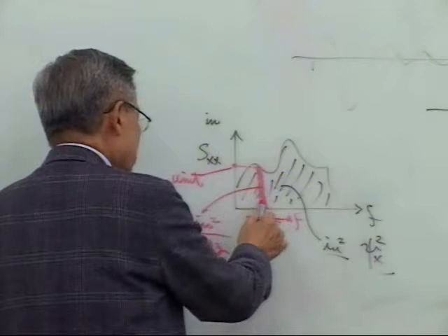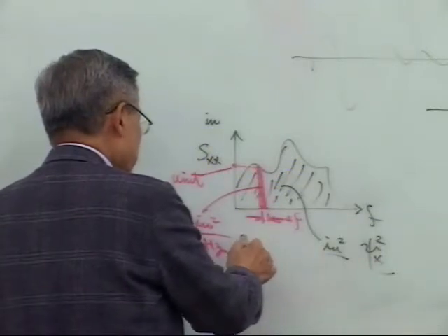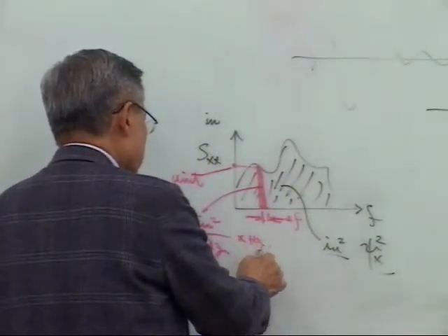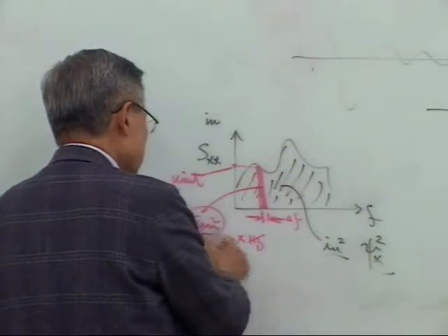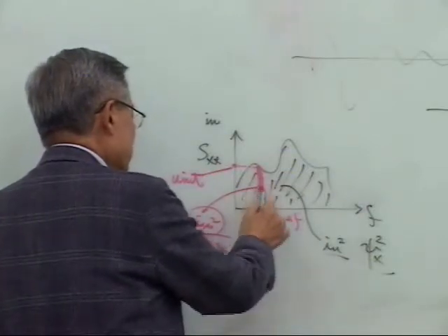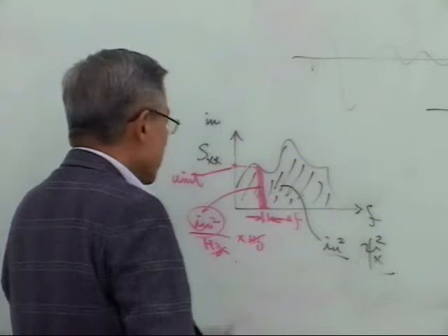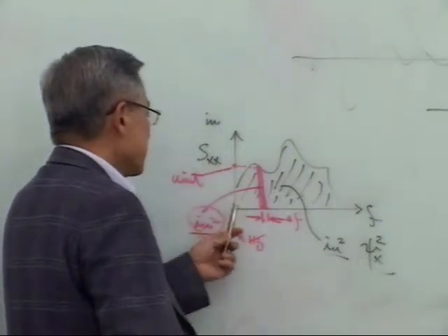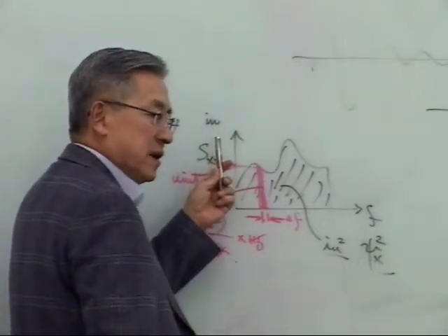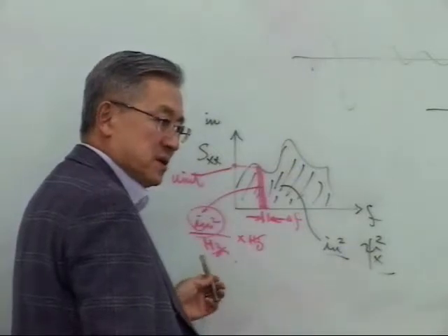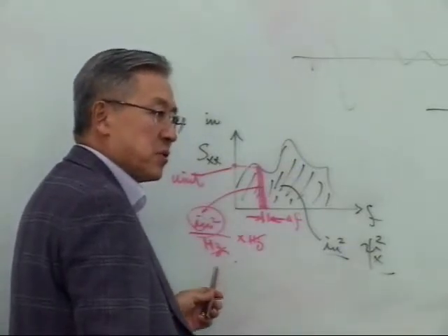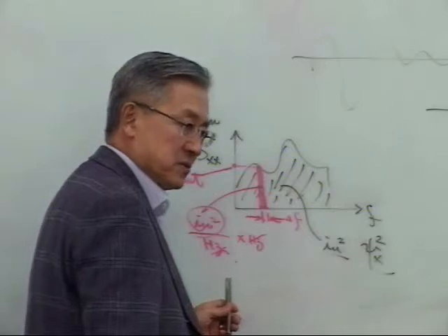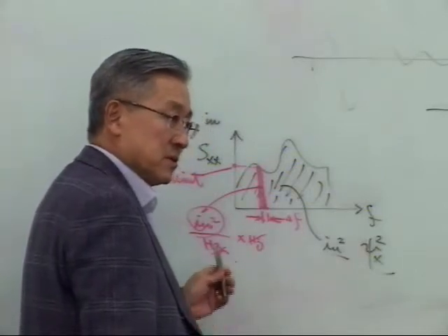Otherwise, when you take the area, you multiply by frequency, hertz, then this cancels out, and you have a mean square value as area. So the unit of the vertical axis has to be, in this case, inch square per hertz, always divided by hertz. Okay, always.